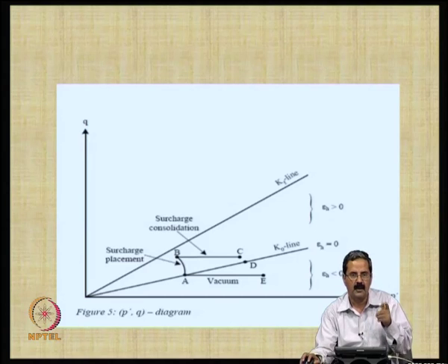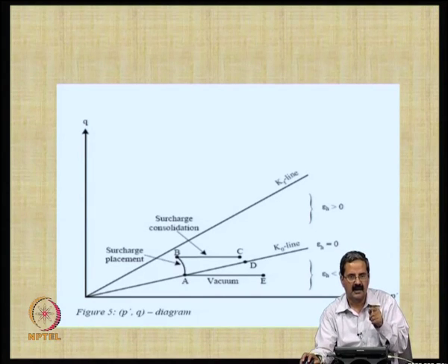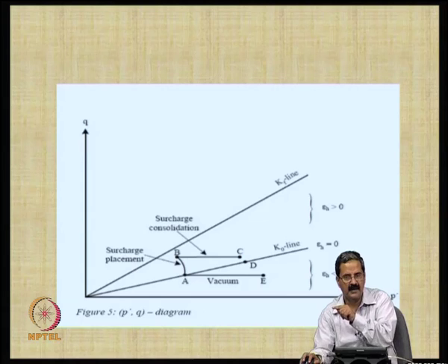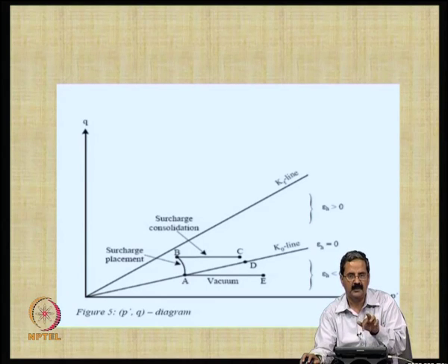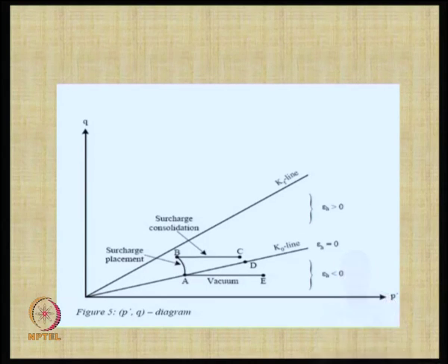So, for example, pore pressure is generated, and you say sigma dash equals total stress minus pore pressure, plus this, which actually becomes additional. So, the effective stress will increase because it is the opposite, it is a suction, it creates a suction. So, in the process the effective stress is increased: the effective stress equals total stress minus pore pressure plus suction.